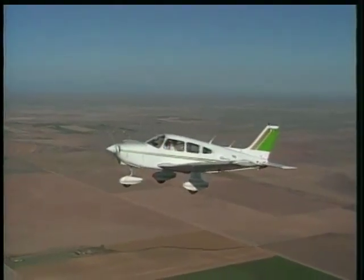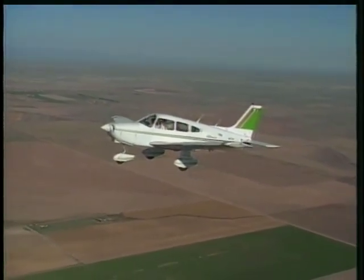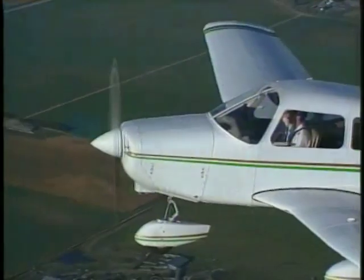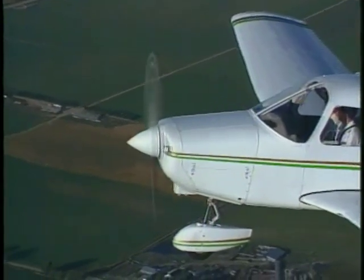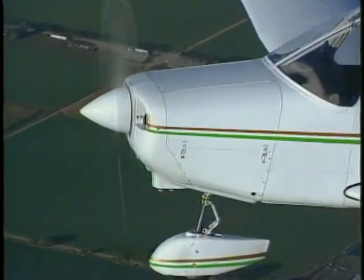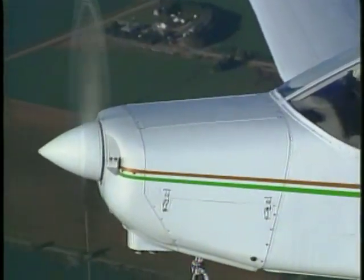Before we get into the mechanics of constant speed propellers, let's quickly examine why they are more efficient than fixed-pitch propellers. Thrust is a product of engine horsepower and propeller efficiency. If a propeller could operate at 100% efficiency, all of the engine's power would be converted into thrust. However, no propeller can attain 100% efficiency. Moreover, a fixed-pitch propeller produces its maximum thrust only at a specific RPM and airspeed.